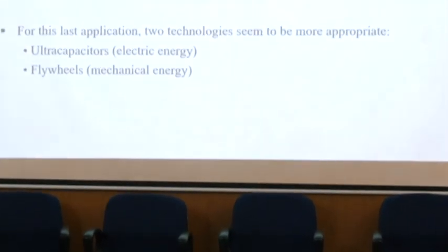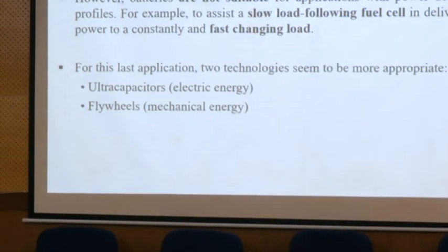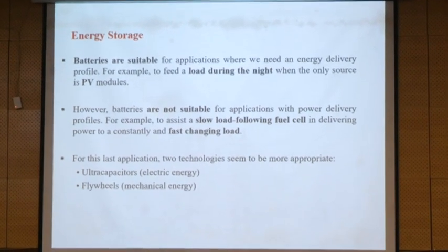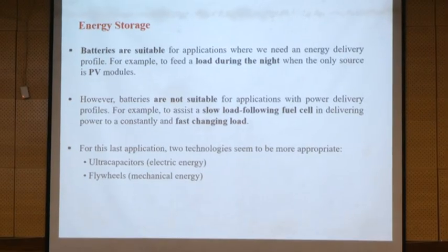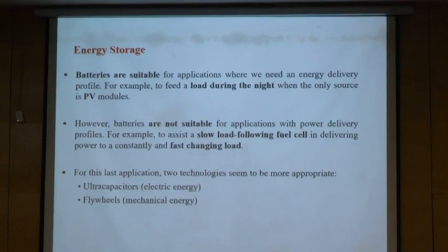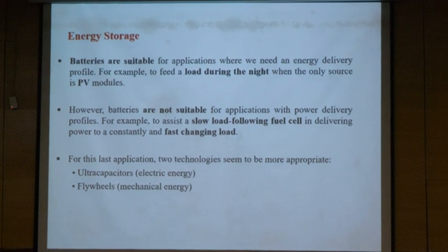The other problem is that synchronous generators are very stable and provide very stable voltage, but converters just have a switching mode, so you cannot predict the behavior of the converter. The dynamic reaction is not predictable, so they also provide some disturbance for the grid.